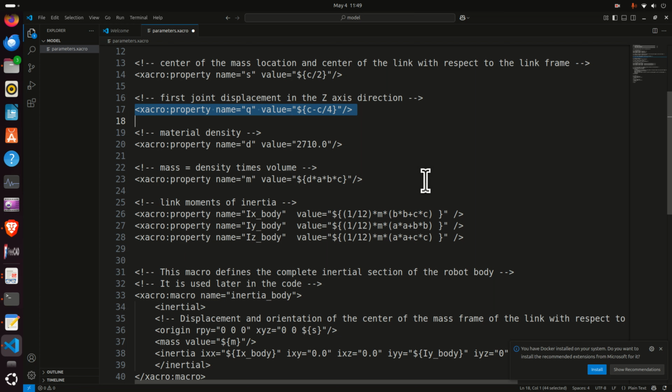When I say the dynamics of the system, I actually mean everything that's on the left-hand side of Newton equations. In the case of point masses, that's the mass. However, in the case of rigid bodies, that's the moment of inertia. Consequently, to define the moment of inertia, we need to define the density, volume, and the mass. So here's the material density. These are the standard SI units. That is, the density is kilograms over meter cubed. You can see that this is a metal.